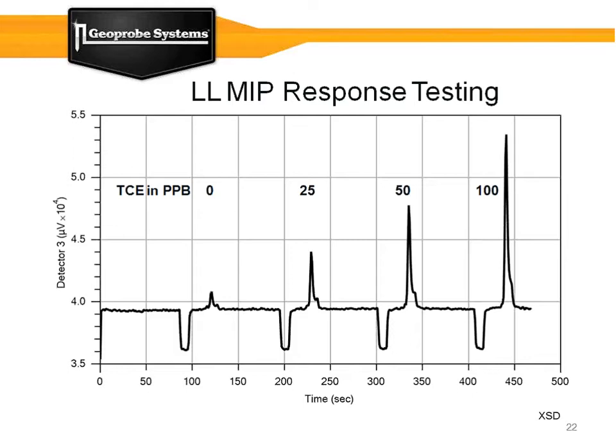One thing I want to add here is just because an operator has a low-level controller, a low-level system, does not necessarily mean that they can see down to these concentrations well below 100 parts per billion. It is very much still dependent upon the contaminant, the site you're dealing with, but most importantly, the maintenance level of the detectors, of the detector system that they're operating. If it's not well maintained, they may not be able to achieve these kind of levels.